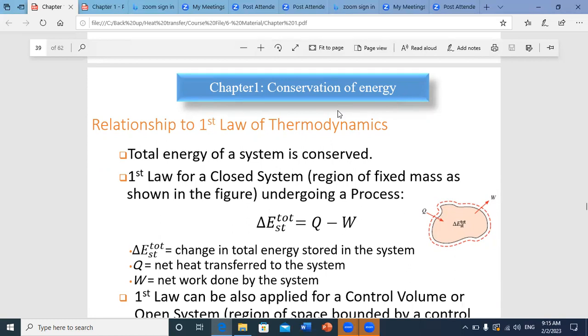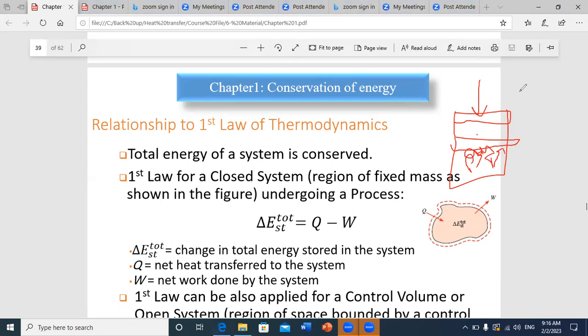How can we have exchange of energy in work form? If you take the example of piston cylinder systems, you have a piston and you have air inside your cylinder. When you press on your piston, you will transfer energy to air because as you put force on your piston, you will compress air. And when you compress air, you will increase its pressure and temperature. So you will increase its energy. So here you increase the energy of air because of a work done by a force.